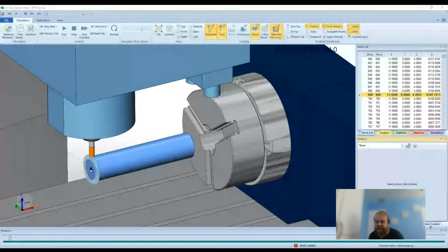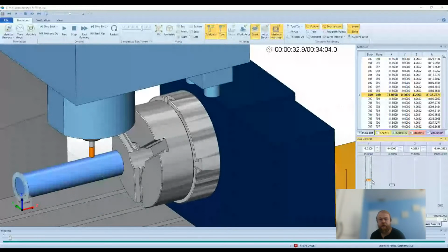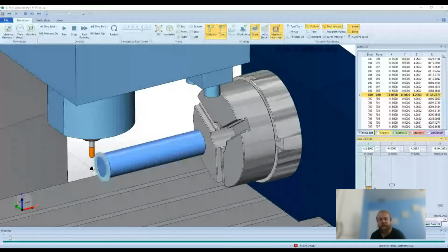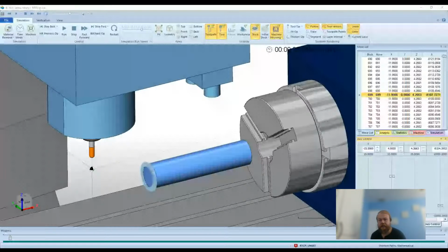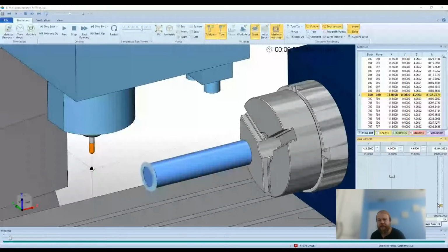That is under axis control. So we went over cut sim, we went over analysis. We'll go to axis control here, where I can move these sliders where we can move this back and forth in the positive or negative X direction, the positive or negative Y direction, positive and negative Z, and the positive and negative A direction, which is just rotating the rotary table there.